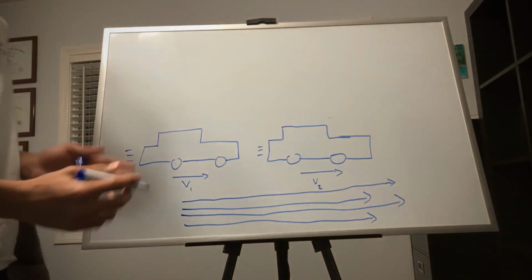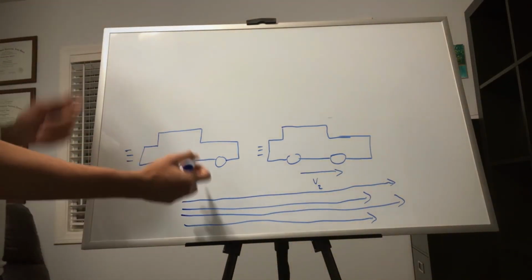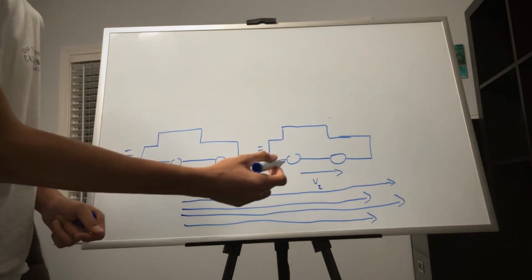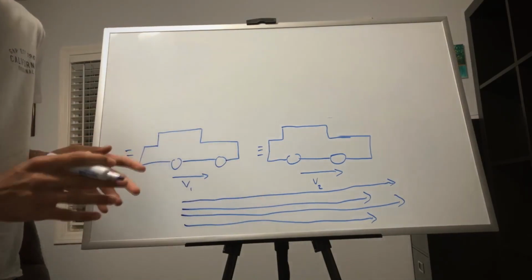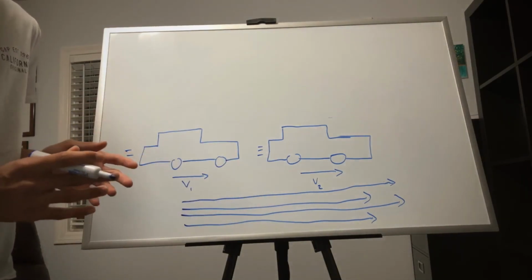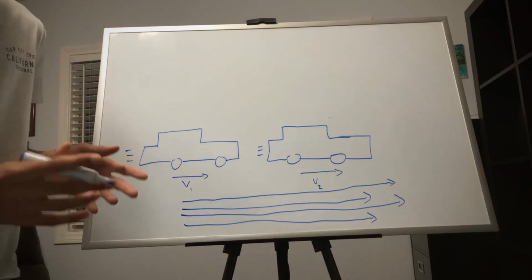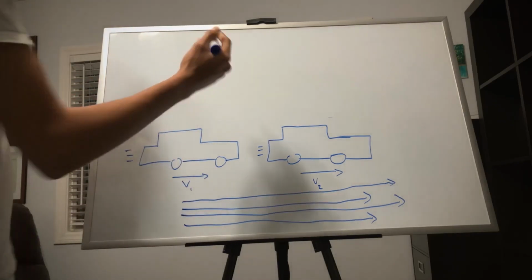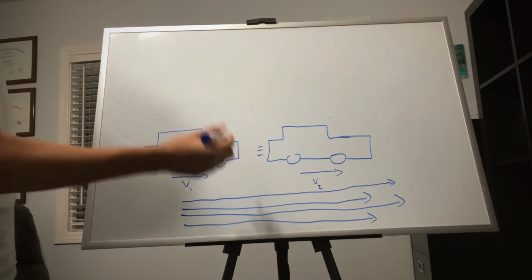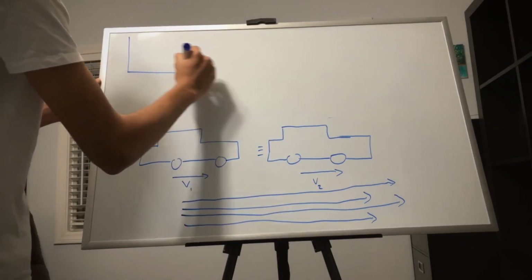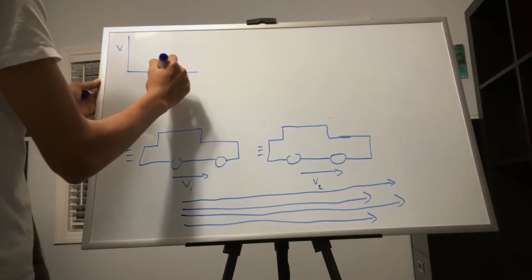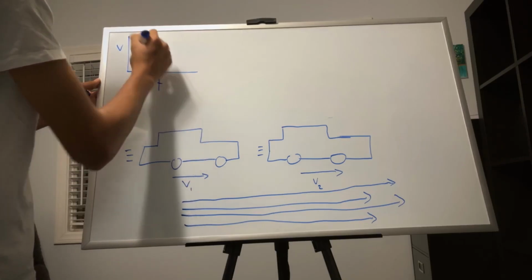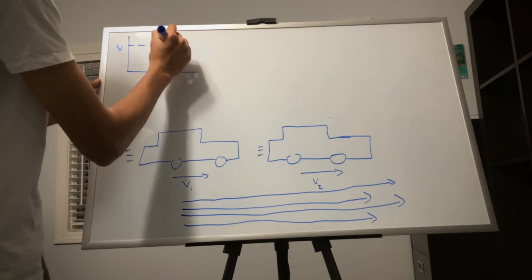So when we have something like this, where this car is trailing behind the second car and is removing some of the error but not eliminating it entirely, this is called steady state error. Let's say we have some other situation, not related to this, where we have a graph of our velocity versus time, and a set point velocity up here.